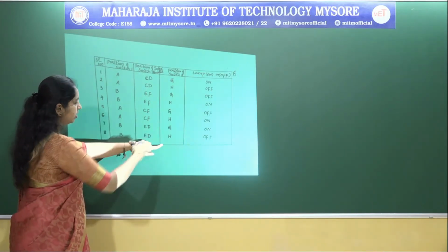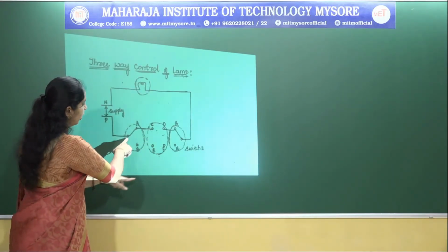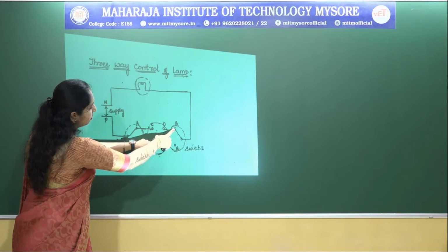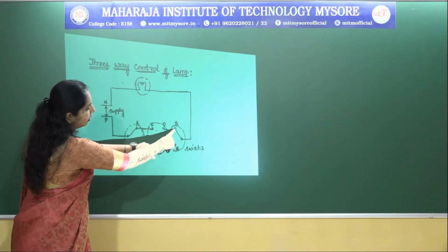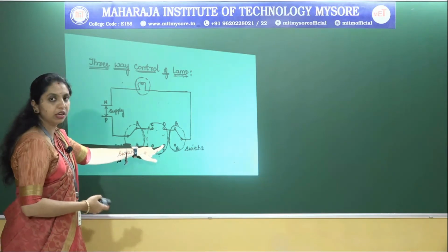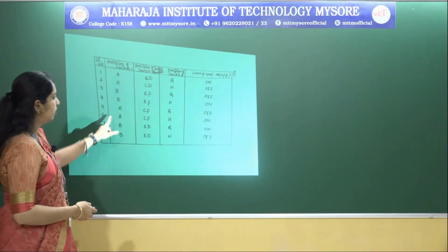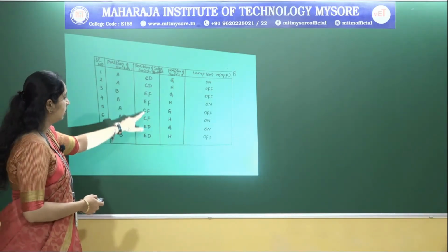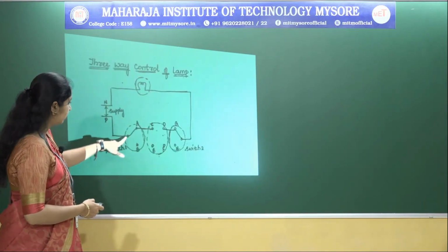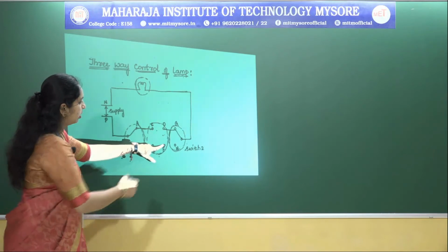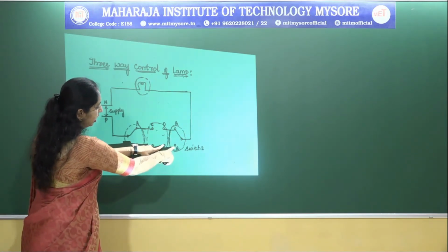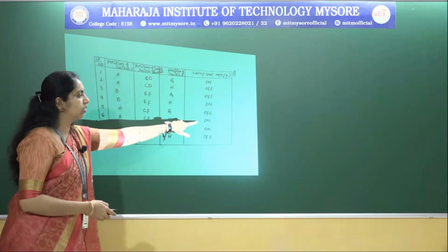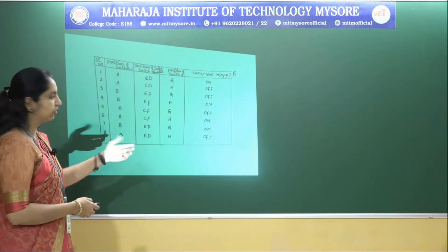Look at this. Now we have it at G. So now we have a connection from A, this C to F, but if we have a connection at this point, there will not be any continuity in the circuit. So it becomes off. Similarly, here the same condition has been taken, A and then CF. Here, instead of G, if we have the connection at position H, then it will get connected. So it becomes a closed circuit, and of course this will be on. Look at the condition of the lamp. It will be on.